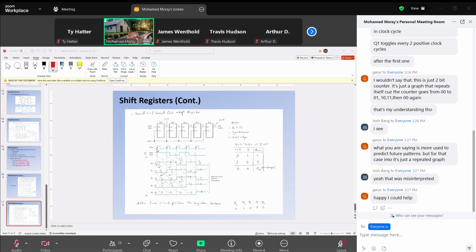again, to determine the output, look at what the input is just before the edge, at T0 negative, as I mentioned. Just before the edge, what we have for D is 1. So 1 appears at the output, and we keep 1 until we reach the next edge. At the next edge, just before the edge, the input D is 1. So 1 appears at the output.